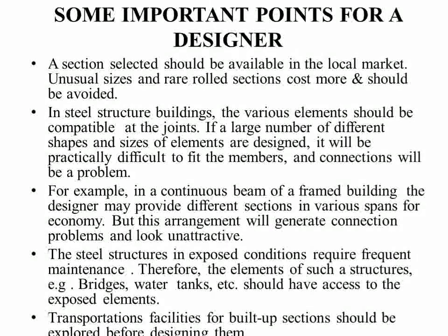Then, as a designer, when you are going to design a steel structure, the designer must keep the following points in mind while designing. First one, the section selected should be available in the local market. Suppose you have selected a section and that section is not available in the market, then we have to manufacture that section, which will cost more.